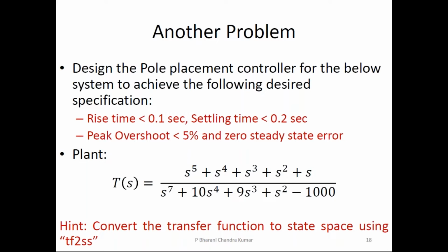You have to take the partial derivatives of this nonlinear equation with respect to the state to get the A matrix, and with respect to the U to get the B matrix. Once the A and B matrices are obtained, the process is exactly the same as what we have done. I have asked you to derive the PID controller for that, but not the feedback linearization method given in that paper. So my idea is, take the nonlinear plant from that paper, do the linearization using the Jacobian approach, and then apply the PID controller. It is not about the feedback linearization or whatever is given in the papers.